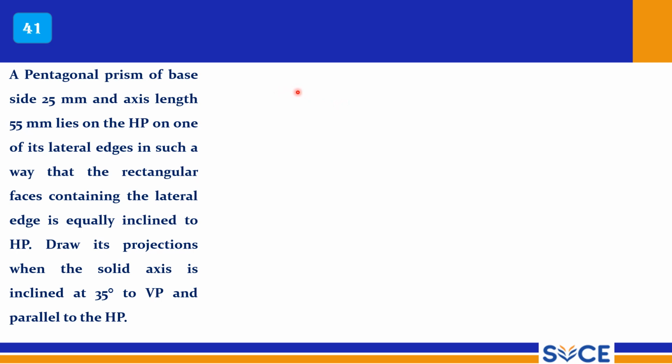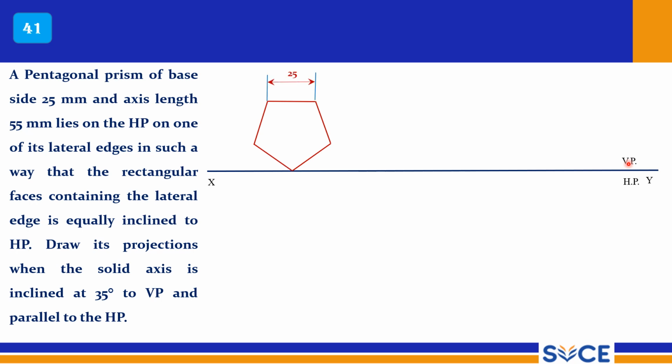Draw the horizontal line here, complete a pentagon, right, and then draw the XY reference line. So that way in reverse order you can come, that will be easy, right? Instead of drawing here, taking this angle may be difficult, right? It is 72 degrees, right? So you can take this angle, right? So this is 108 degrees, and this is 108 degrees, and for this it should be the angle. You should compute the angle, right, to start in this procedure.